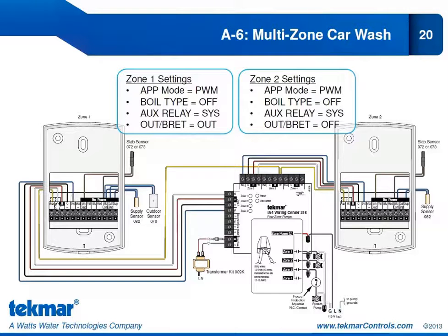We're using our heat relay for the W call on the 316. Now we'll look at the Zone 2 654. Again, we have R, C, and TN4 coming into R, C, and TN4 on the 654. And again, we have our heat relay coming in for our W on the 316.